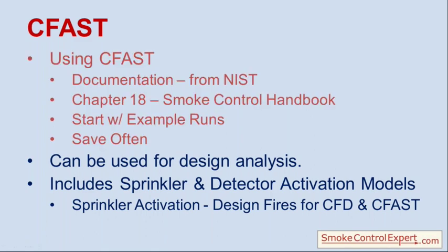Using CFAST, you want to use the documentation from CFAST, the user guide. Also, Chapter 8 of the Smoke Control Handbook has some additional information relevant to smoke control use. Start with the example runs within CFAST, and then go ahead and modify them. That is clearly the best way to go. And save often.